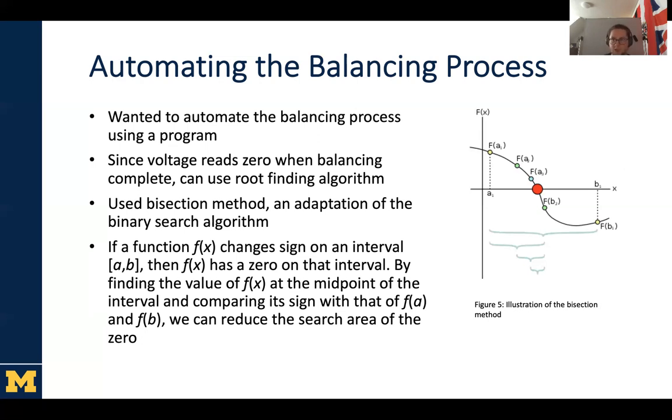We first adjust the phase of Vx by finding what phase causes the Y channel of the lock-in amplifier to read zero. Then we adjust its amplitude until we get the X channel to also read zero. Then we have both channels reading zero, then we know that our circuit is balanced.